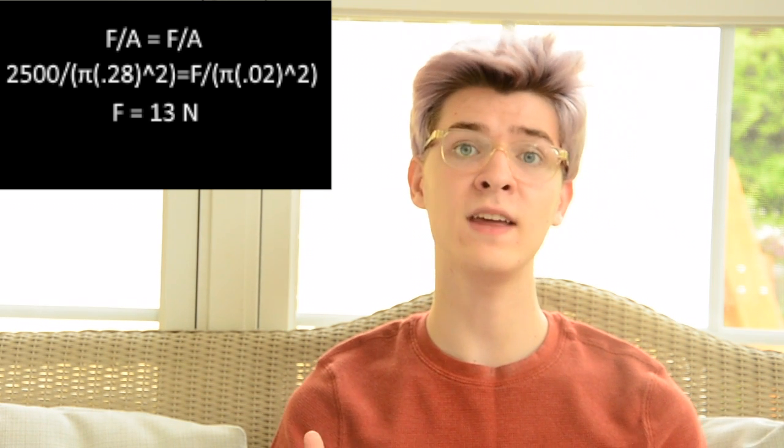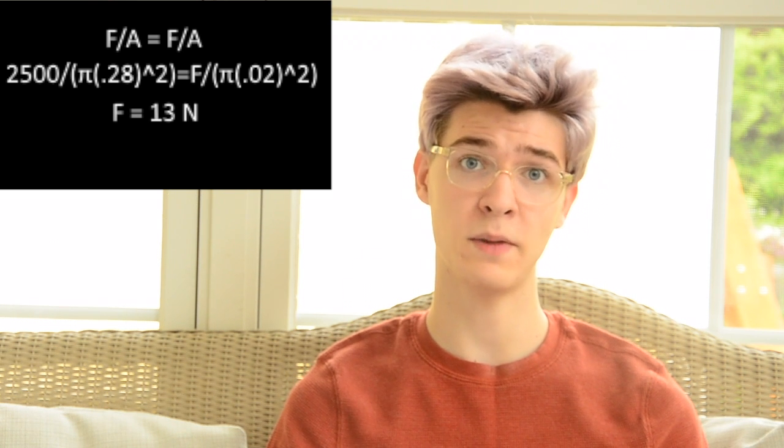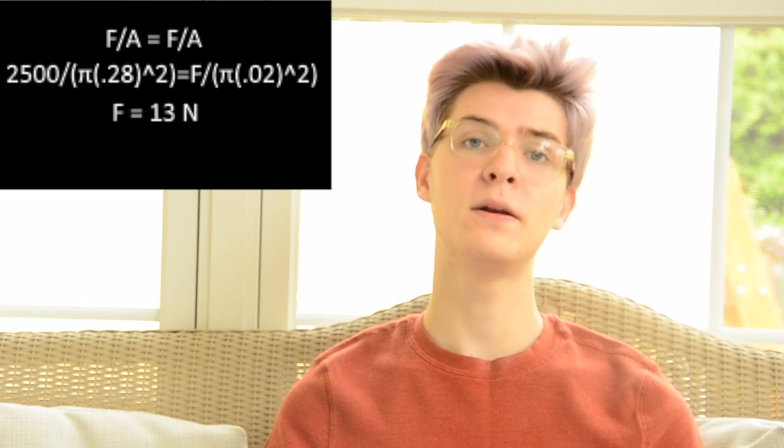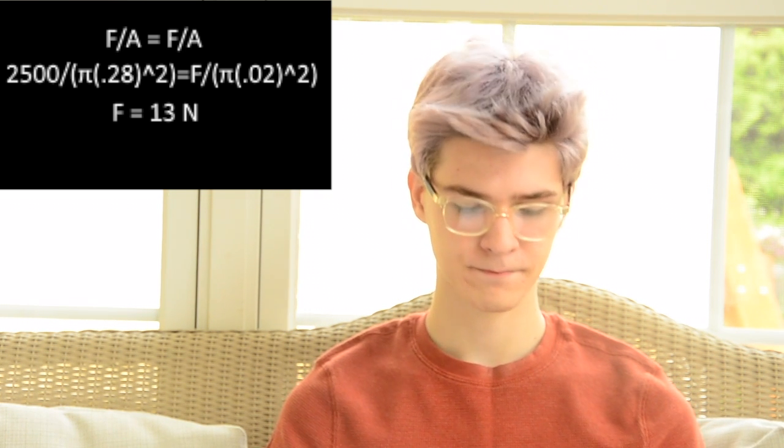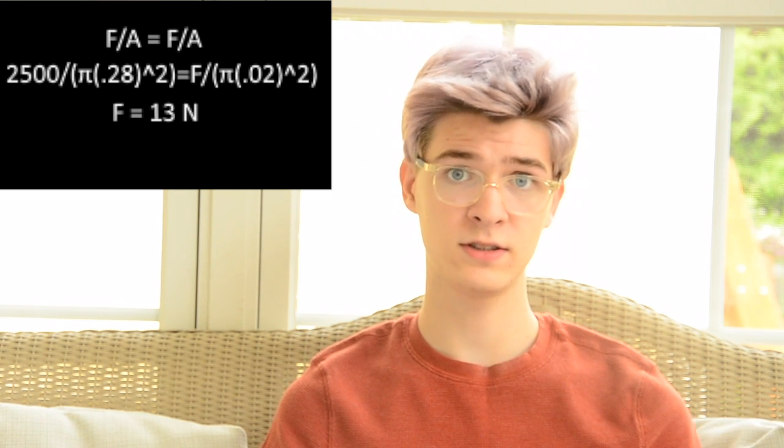First, we find the cross-sectional area of both of the pipes, meaning we use the radii given to us to find the area of a slice of each of the pipes. Then we can set up a proportion that says that the input force over the area of the input piston equals the weight of the elevator over the area of the lift piston. Then, by plugging in the weight of the elevator, the area of the lift piston, and the area of the input piston, we can find the minimum force needed to lift the elevator. After rearranging the equation, we can see that this force is about 13 newtons.